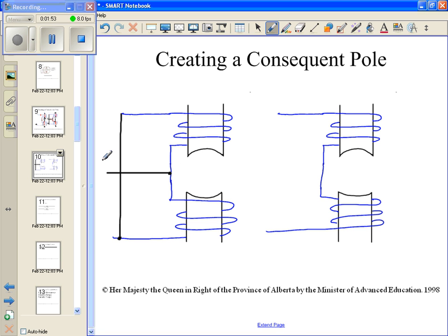We're going to freeze frame that AC sine wave for a fraction of a second, and assign a polarity of negative there and positive here, and look at electron flow. Electron flow, again, is always from negative to positive. I'm going to switch colors here to show electron flow, and let's see what happens. So here we go with electron flow traveling this way. Again, we reach a junction point, and at this junction point our current splits. Some current flows that direction and some current flows that direction.